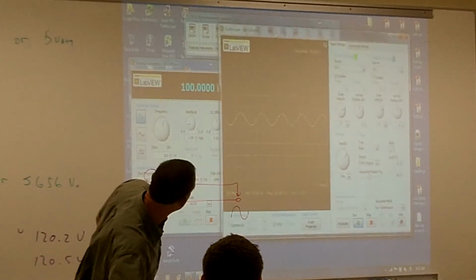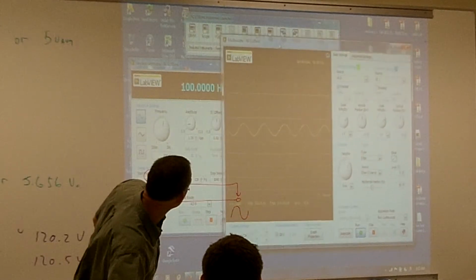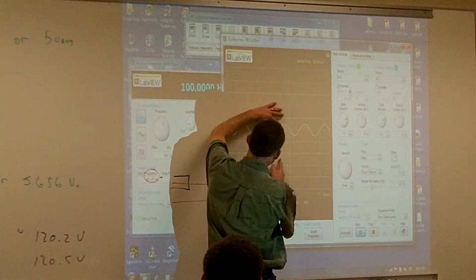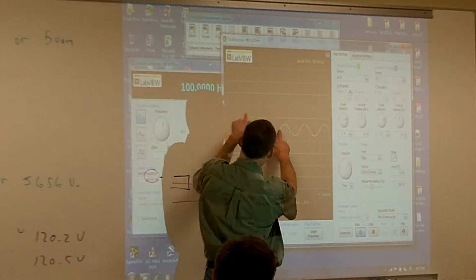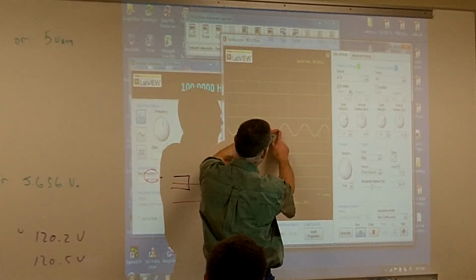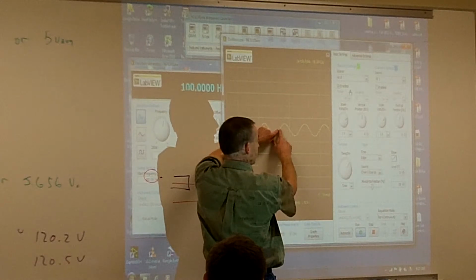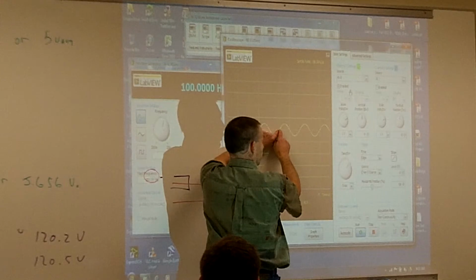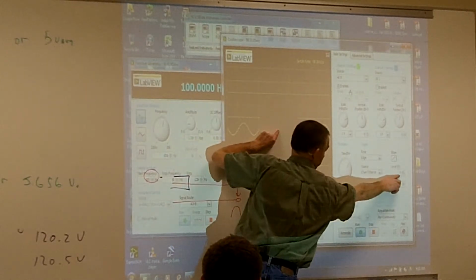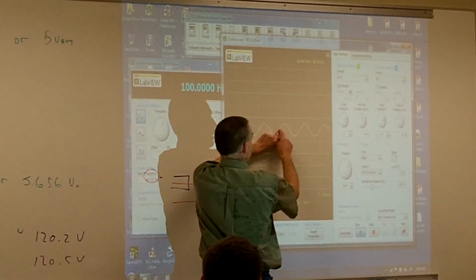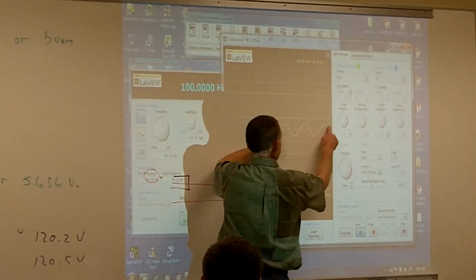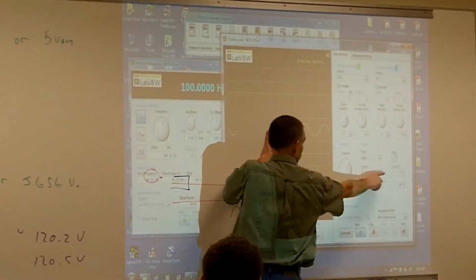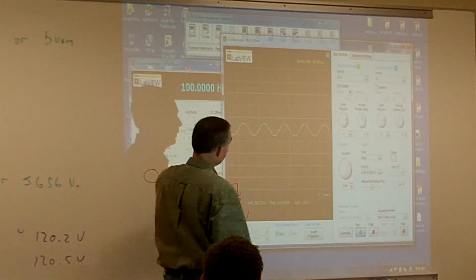So if I can't see it, that's bad. Oh, there you go. I didn't keep it moving. So there are two crosshairs here, one vertical and one horizontal. That crosshair is where the oscilloscope is told to start to draw the signal. The signal's actually starting right here, at the 0 reference, because that's the level I told it to be at. So right when it goes just above 0, it starts drawing this picture out. And it keeps on going, and every time it goes just above 0 on a rise, it's going to redraw it.